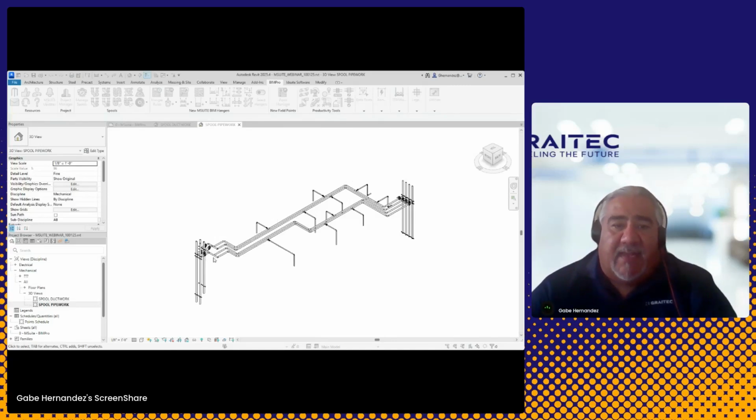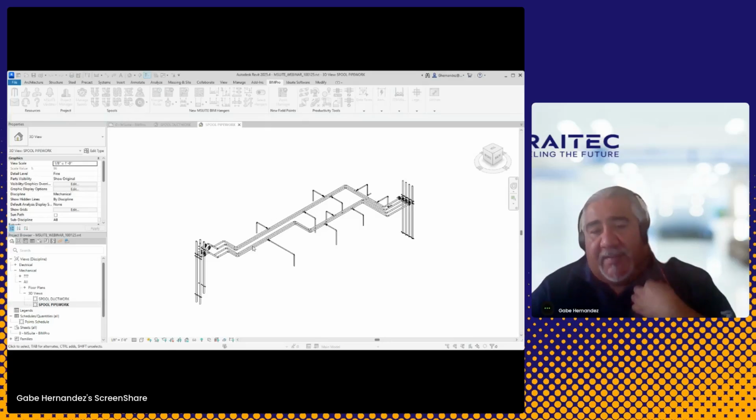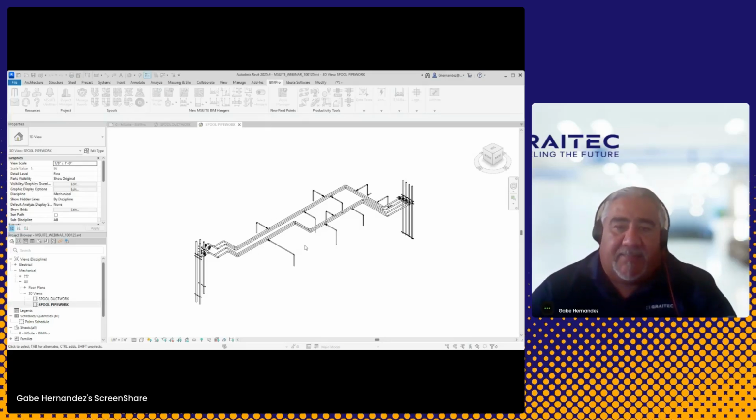Down here at the bottom, I have the ability to, when I set a maximum length for spools, decide what it does when it comes across something either shorter or longer. Exclude the pipe. Do you want it to take the entire pipe or split the pipe up at a specified length? And that's in decimal feet, and you can type that in here.